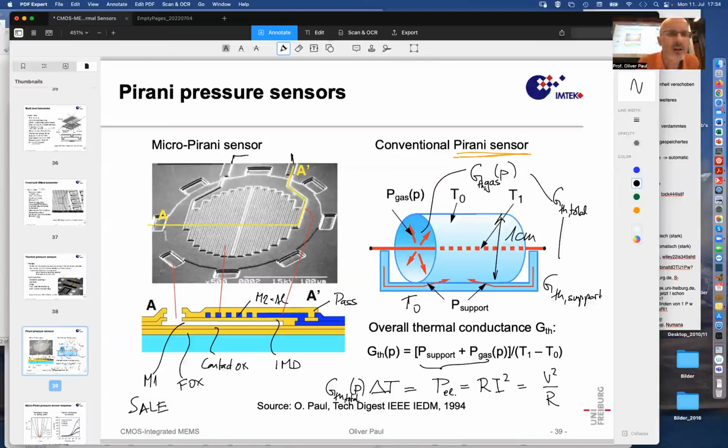And if I do a cross section across this structure, you will see many little cross sections through that line. This is symbolized by these cross sections through the line. And then at this point, I follow the line to go from the meander out towards the external side. And then for sure, there will be some contact pad to do some measurement with the bond wire out there. And the same here. So there's another bond wire to do the measurement, hook it up to some instrumentation.